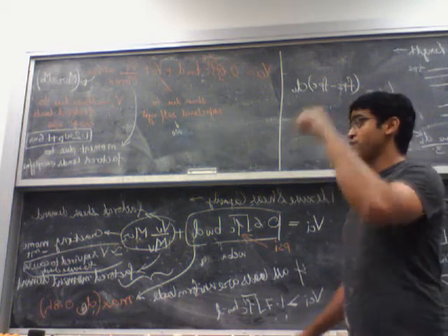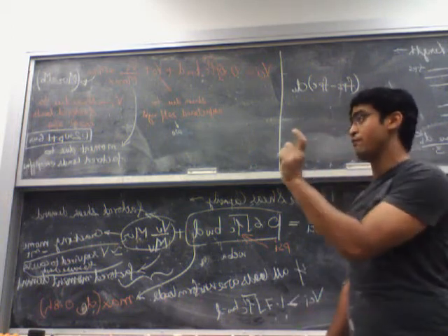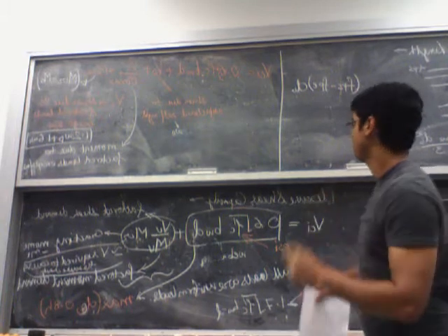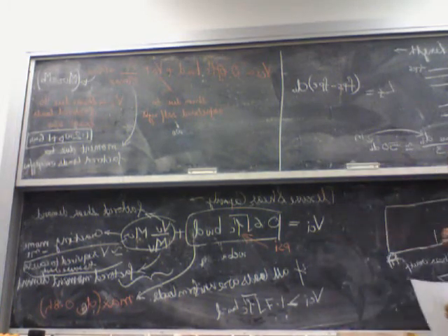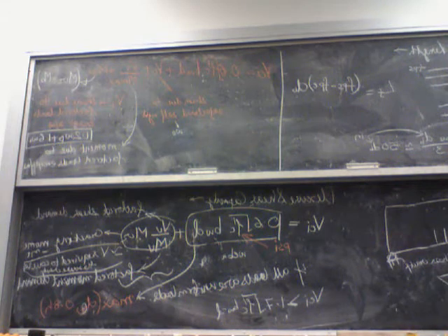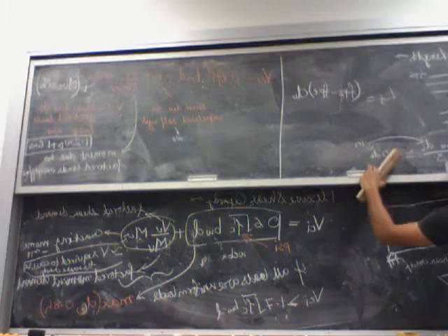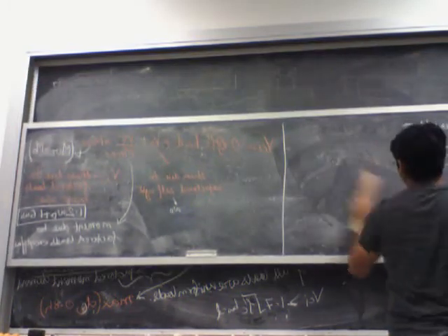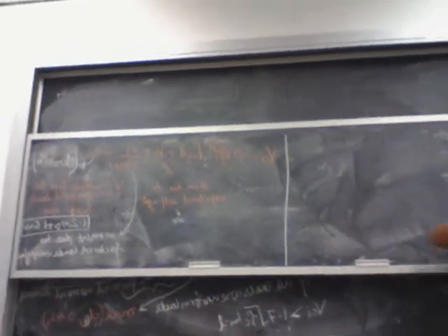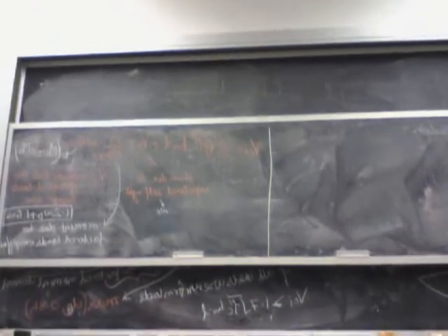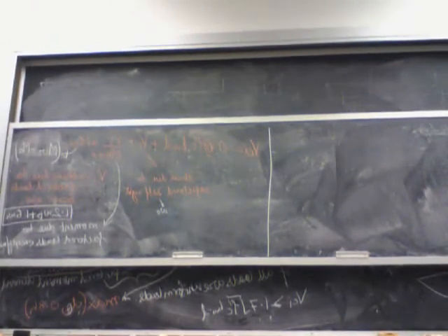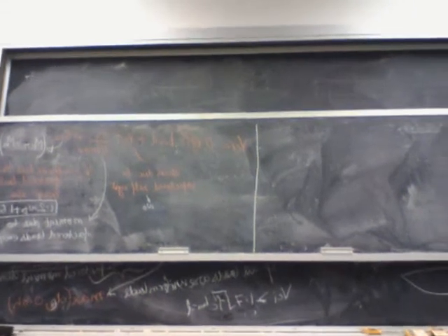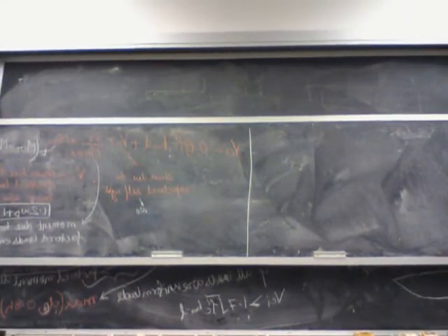It's the web width. If you have a flange section, BW is the web width, not the flange. Okay? So this gives you the VCI, which is the flexure shear capacity. Now we need to find out what the capacity is for just the shear cracks. So for the